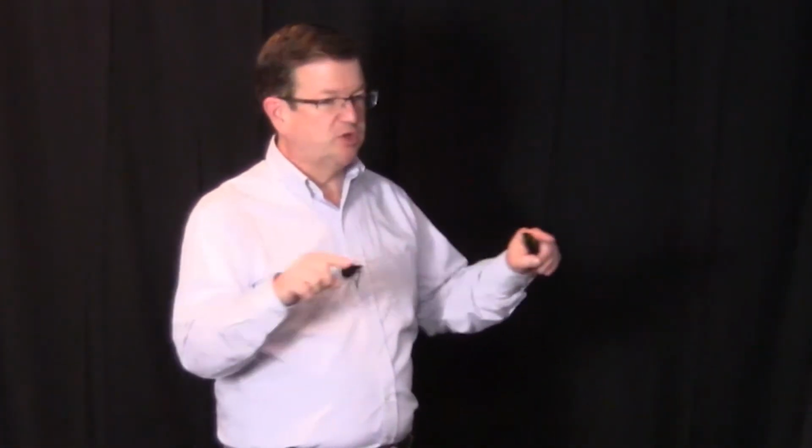So what do you do? You just analyze one phase. It's not a line to ground calculation. It's a per phase calculation. So you analyze what's on one phase, and then what you determine on that one phase is also the answer for the other phases. And so when we're performing the calculations, like I had up here on the screen, the voltage that we're looking at across one phase is the line to neutral voltage.